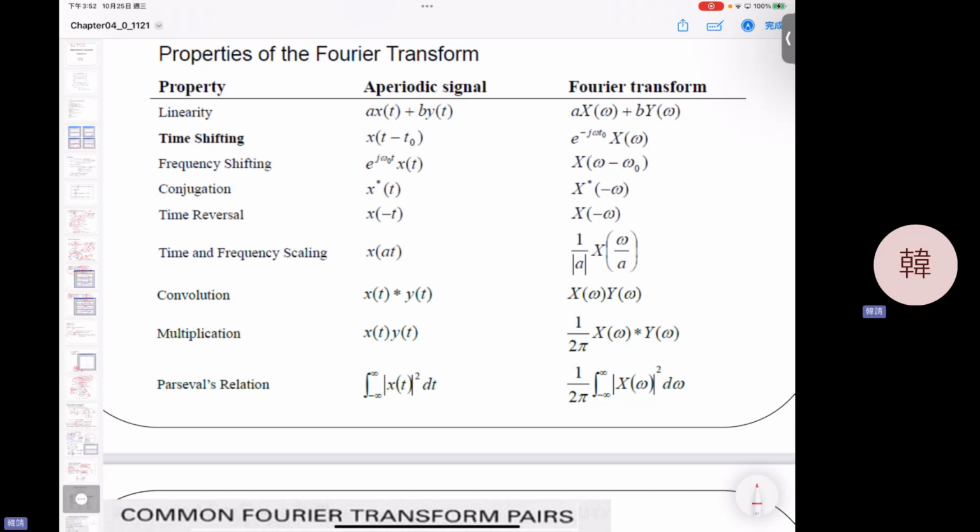If you have very dense, very quick, very short sampling time, in the frequency domain the copies become wider apart, sparse. So they will not overlap, and the convolution will be fine. But if your sampling time is too large, the resolution is too low, you have trouble in the frequency domain, and some problem will happen.